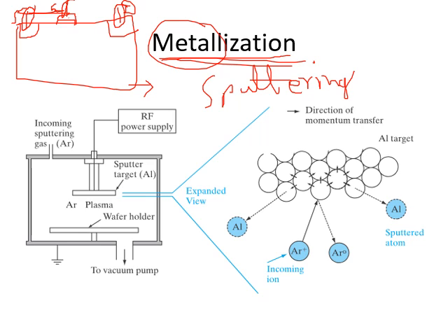So we have argon plasma, you are seeing here, and we are immersing the aluminium into the argon plasma. So what happens by that? Argon ions bombard the aluminium and physically dislodge the aluminum atoms by momentum transfer. Means these argon ions try to dislocate this aluminum.